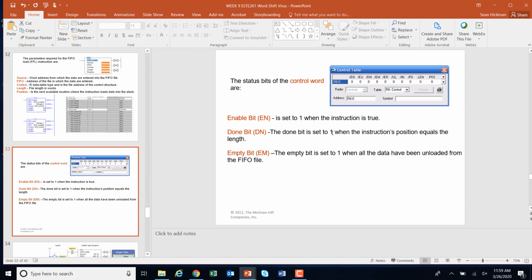Once you got 5 plates in a stack, that control gets done, and then you can know that your stack is done. At that point, maybe you want to use that done bit so that when a new plate comes on, you unload the plate off of the bottom. Maybe that means it's dry. So put a new plate on top, take one off the bottom, okay? So that's how this will be explained later.